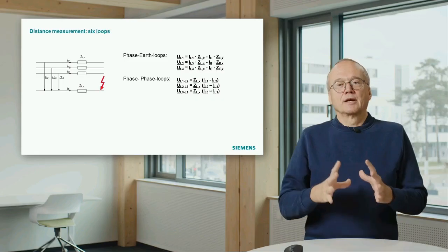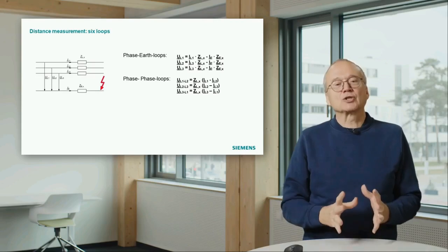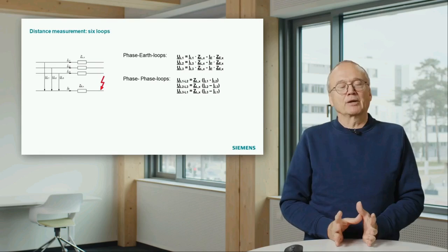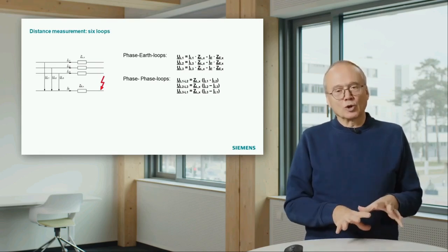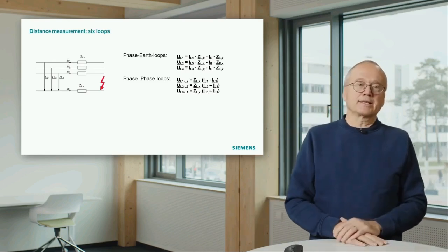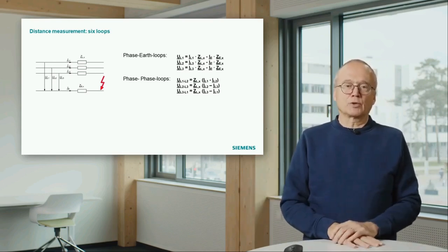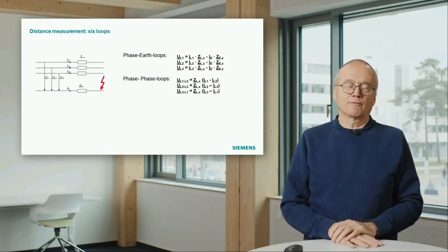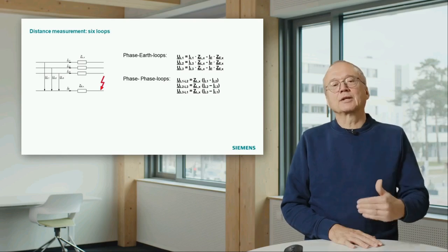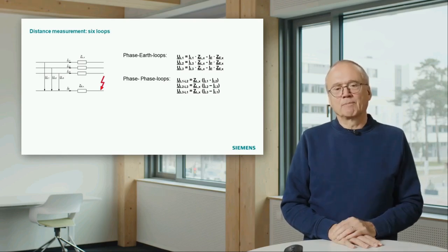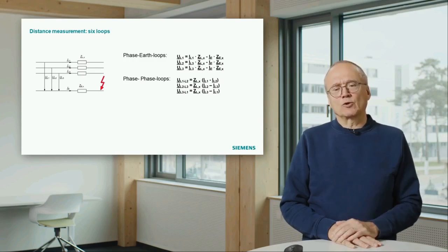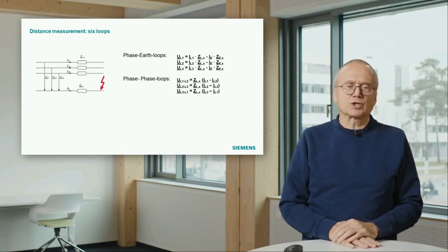That means a normal protection relay has to deal with all these 6 impedances in parallel. That's a bit of workload for the relay, but in most cases we don't have to consider this in the following slides. Normally modern relays always handle these 6 loops in parallel. You may still have some relays in operation which are called switched relays.